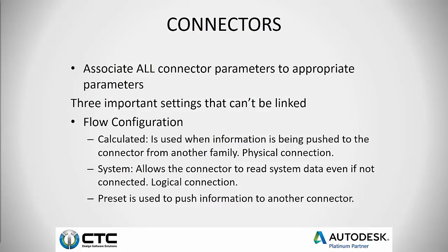This is how we push our information from one family to another or into a schedule. And when we have our connectors, we need to associate all the available parameters in the connector and link them to an appropriate parameter within the family itself.